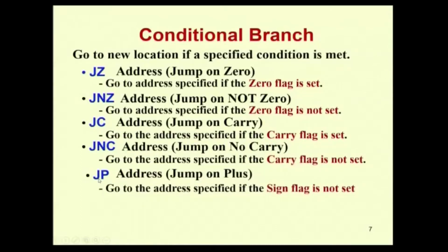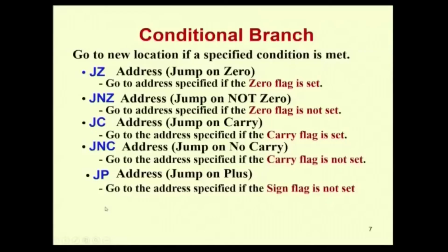The sign flag represents the sign. We use it to represent positive and negative numbers. A digital computer knows only 0 and 1, it does not know plus or minus. So, we have to use one binary digit, the most significant bit, as the sign bit in signed arithmetic operations. If the sign flag is 0, then it is positive. If the sign flag is 1, then it is negative.